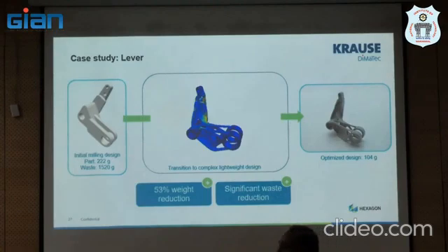This is very much valid for a carbon fiber composite. Now I know the strength required, so I can develop my own material with a different orientation. That is more useful for a composite, as you rightly mentioned. Now I know the optimized geometry, so I know what the material strength should be. Now I go back and develop my own material. That can be done, and it is easy for a composite and other things. But in metal, it is very hard to come up with my own material grade.